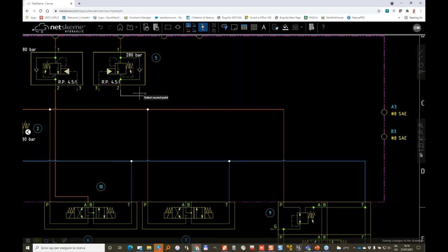There is always a logic in the connection line. So if we start making the connection from B to 2, the connection is made longest segment first and then the short segment. In this case, since I need room for the pilot lines, I start making the connection from 2 and end with B. This will come with a bit of usage, and you will get familiar with it.